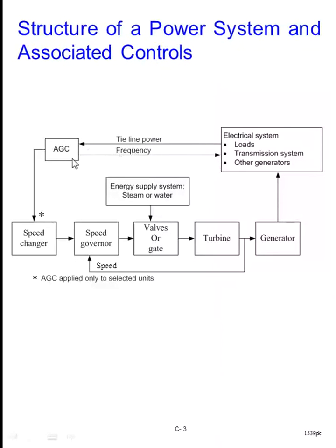And then we have a load system. We have a subsection, you can say, that we call AGC, automatic generation control. And this will feed a signal to the governor part here. So you can see here that there is another loop. This is the primary loop to the governor section, with the feedback signal information of frequency and the tie line from the network.